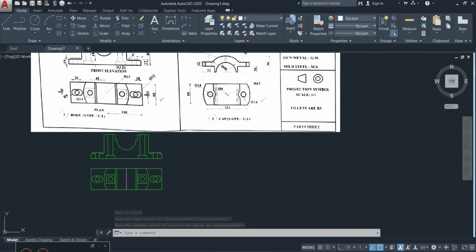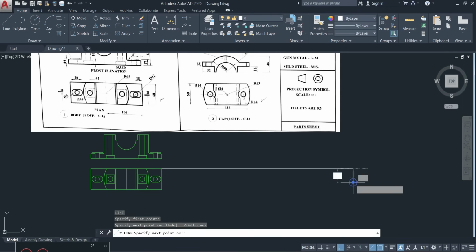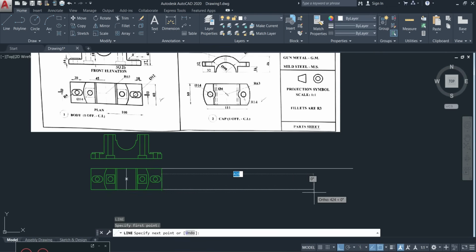Alright, now because this is an orthographic drawing, all I'm going to be doing is projecting lines across like this for the plan view, that is, and I'll just draw within the space there. Alright, that's what I'll do. Just like that. Now believe it or not, you see this entire part here is actually a replica of this entire part here with some slight modification.